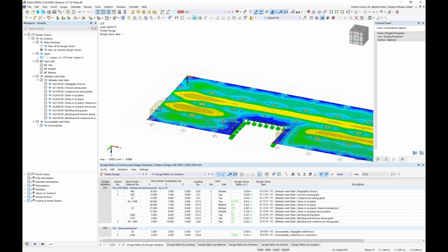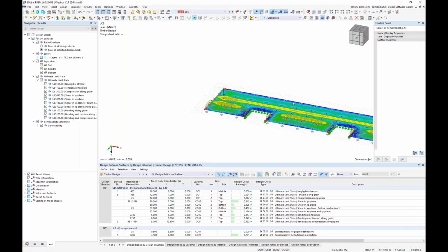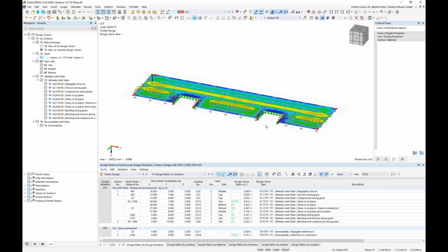Therefore, I'm just using it in Y direction, not in X direction. Because if I did that also in X direction, I would have 10 or 20 load cases, and the calculation time would just increase. You can compare it with a continuous beam. If you have 2 fields, you also have to introduce the live load on the left side and on the right side, because the highest force in the middle support will be with live load left plus live load right, but the highest field moment is with the force on the left side, if it is the longer span, for example. Okay, so I hope that's clear.